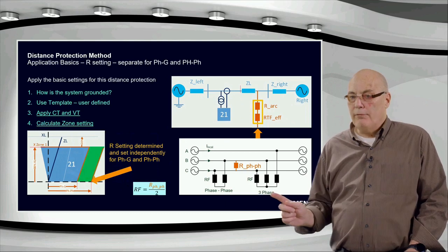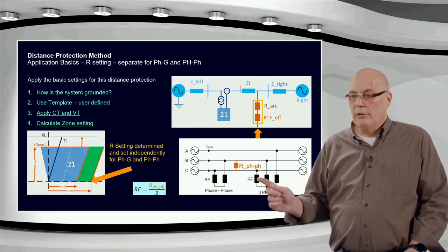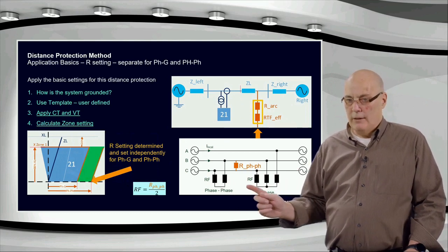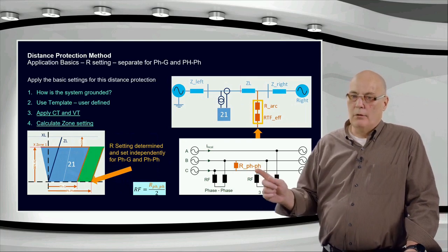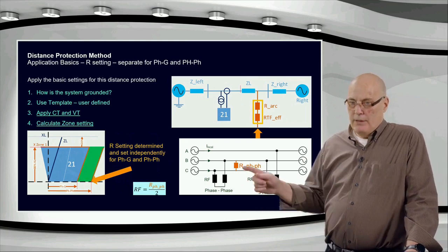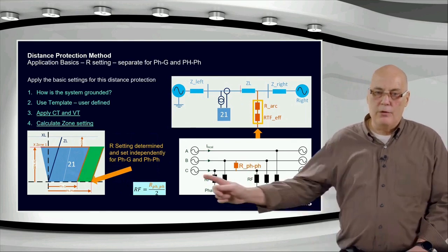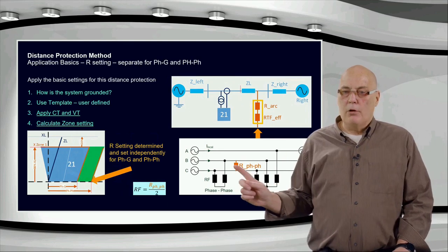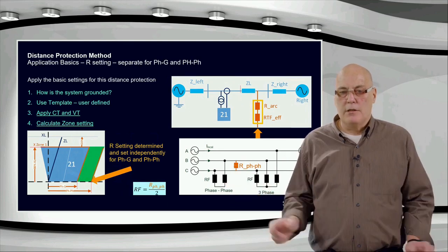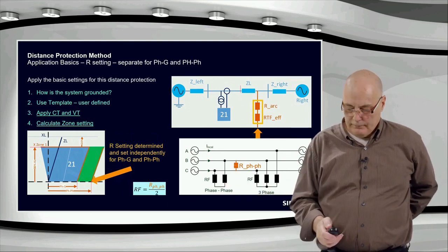So if you have a three-phase fault, the fault resistance definition is exactly the same as for the two-phase, but it's this black one, not this orange one. That is what's measured. So if you see a diagram like this, then you'd actually be measuring only half that, and your setting would be half this orange one, or effectively, this is the setting you would require for phase-to-phase.